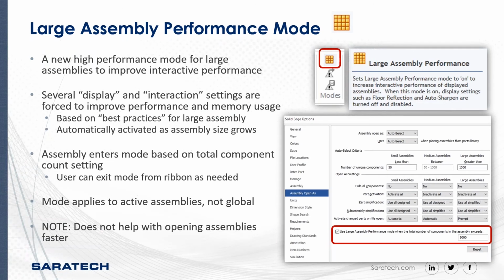So, large assembly performance mode. This is where we get into parts that are very large. I know in the past I was working with Mack trucks, and we'd load up a whole semi truck into Solid Edge, and the performance would slow down. Now we can add the large assembly performance mode to it, and they'll load a lot faster. So it's the new high performance mode for large assemblies to improve interactive performance. Several display and interaction settings are forced to improve the performance and memory use, based on best practices for large assemblies.